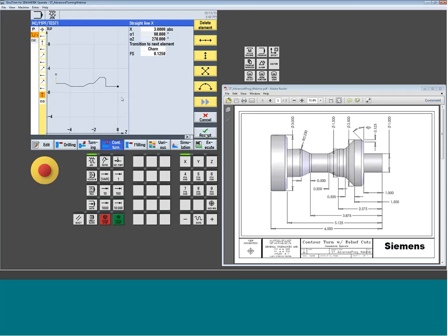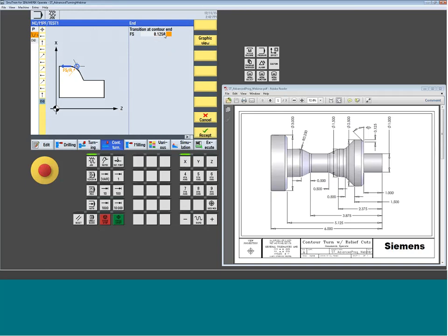But what you do is you have to go to the end field and see how it transferred the chamfer in. When I edit this, like in the start element, I can tell it the direction I have to move that chamfer in. And of course, if I pick the wrong arrow, once I hit accept, I'll see the chamfer won't either come up or it'll show the wrong direction. But you can do end chamfers. You just have to remember to go into this little end field and edit that.